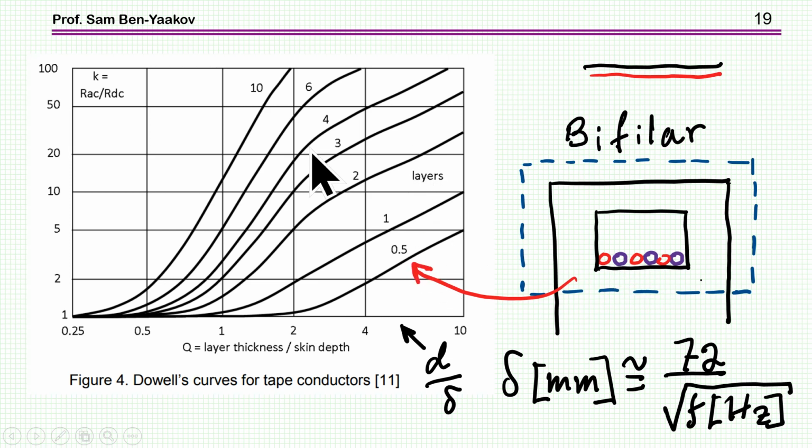And this is why, relative to all the other cases, the RAC is much lower. So this is really actually the best thing to go. But of course, we have problems here of insulation, first of all, between primary and secondary. There's also the problem of capacitance between the wires. So in many cases, you would avoid this and rather have layers rather than a bifilar, in which you wind it with the two wires together here.